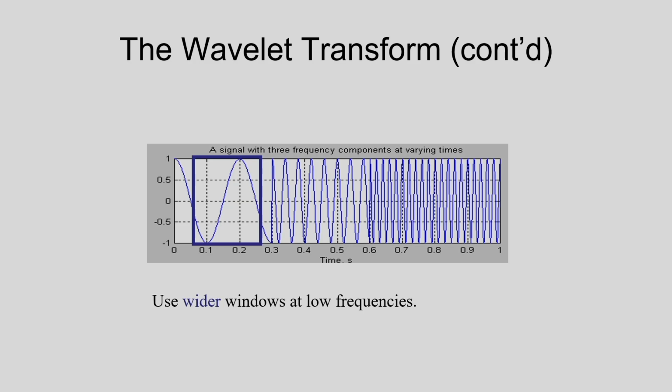That is why the window size is not fixed in the case of the wavelet transformation. I am considering variable size windows: narrow windows for the analysis of high frequency information, and wide windows, which are good for low frequency signal analysis.